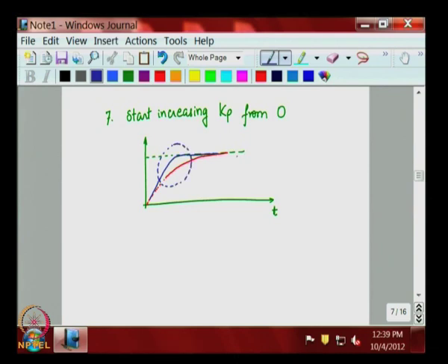Steady state is still governed by the integrator portion, and this is due to the P. So, this is what you would see happening when you keep on increasing Kp till you reach a satisfactory response in a visual manner, and freeze Ki and Kp value, and these values of the Ki and Kp are the ones which you will be using in the controller.